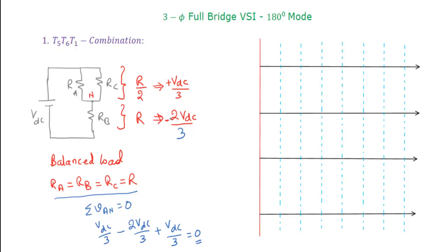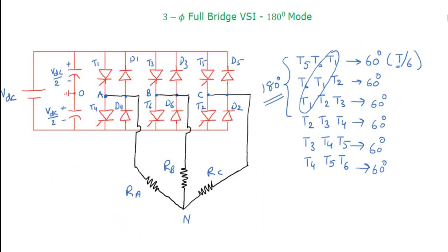Now here we are going to draw 4 voltage waveforms. If you look at the circuit diagram again, one voltage we will draw is called pole voltage. Pole voltage is nothing but the voltage difference between the middle point of the leg and the center point of the capacitor potential divider.